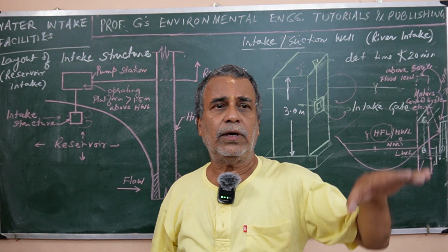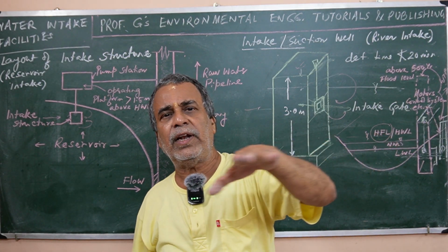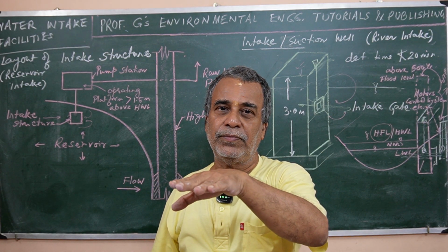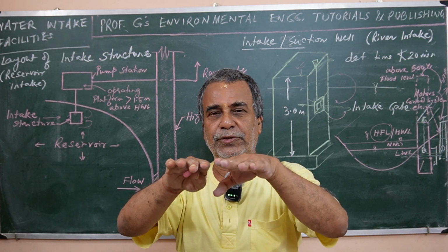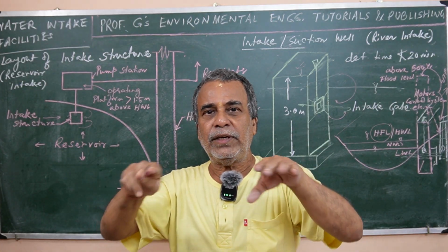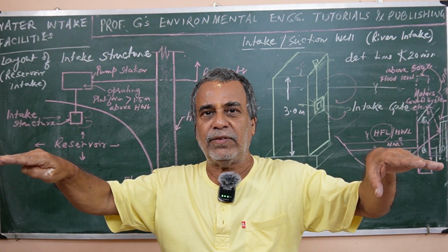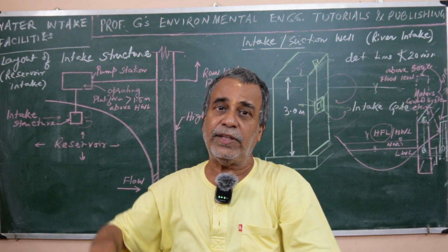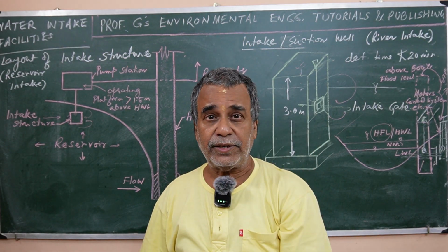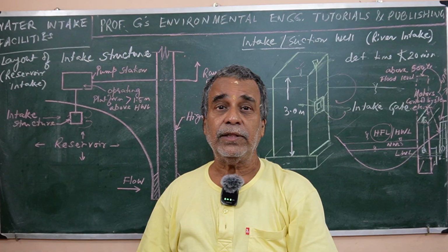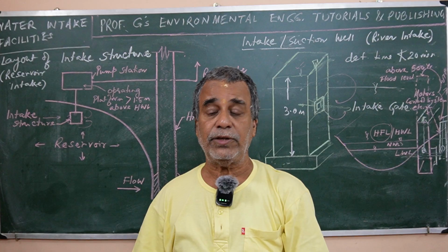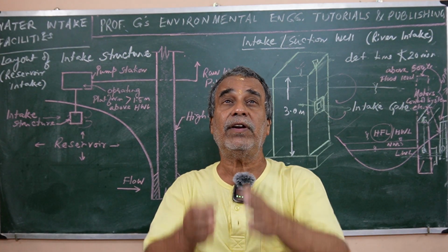In terms of structural stability, if you keep multiple intake gates at the same horizontal or vertical level, there is a possibility of cracks developing, because that line would be a very weak line structurally, and as a result this may develop cracks.